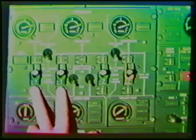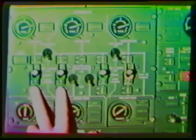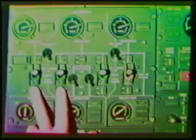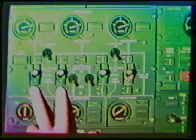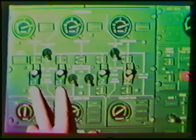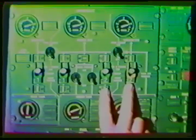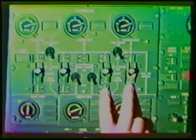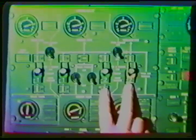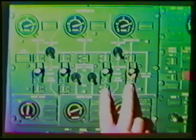On the left of the control module are located the two engine pump selectors for number 1 engine. One selector for the blue pump and one for the green pump. The guards on these selectors are color-coded appropriately for the two hydraulic systems. On the right side of the control module are the selectors for the pumps mounted on number 2 engine, one green and one yellow. Again, notice the appropriate color coding on the guards.